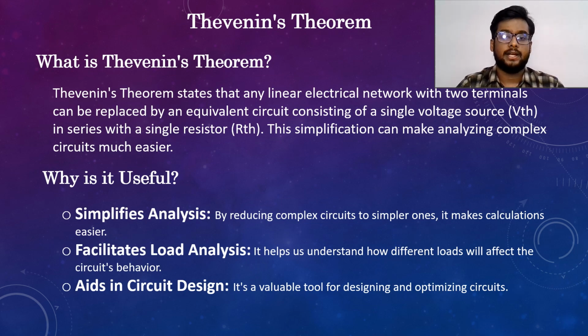My second topic is Thevenin's theorem. What is Thevenin's theorem? Thevenin's theorem states that any linear electrical network with two terminals can be replaced by an equivalent circuit of a single voltage source VTH in series with a single resistor RTH. The simplification can make analysis of complex circuits much easier.